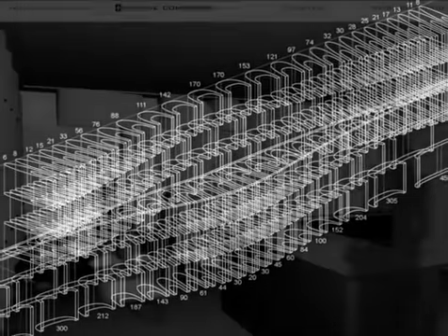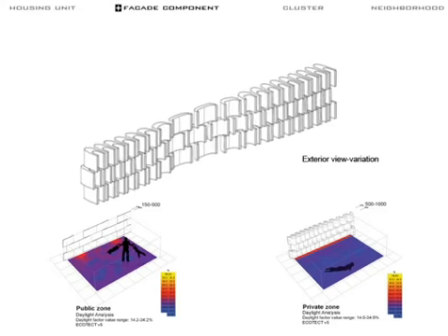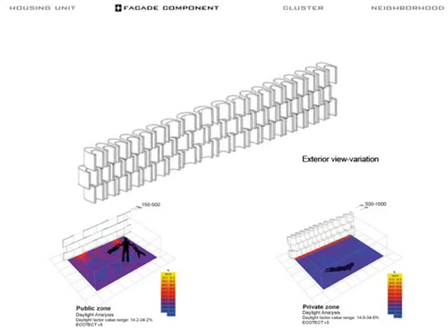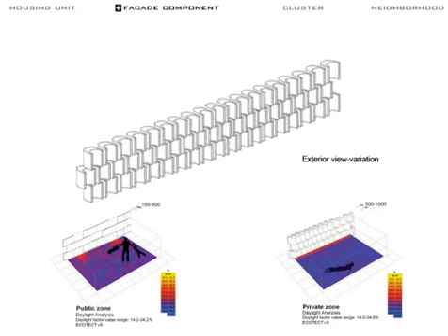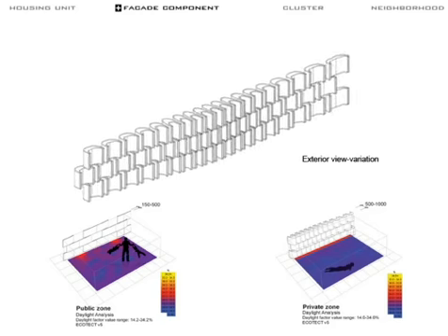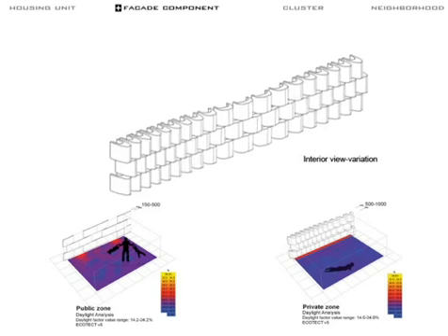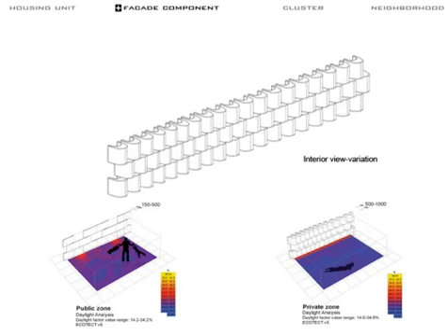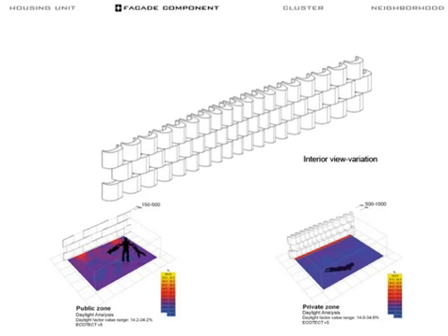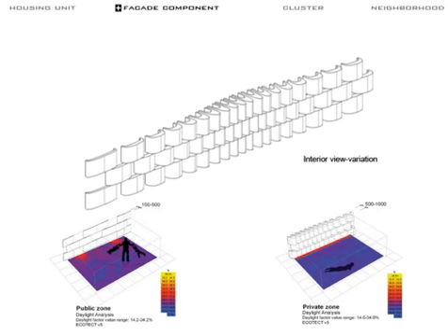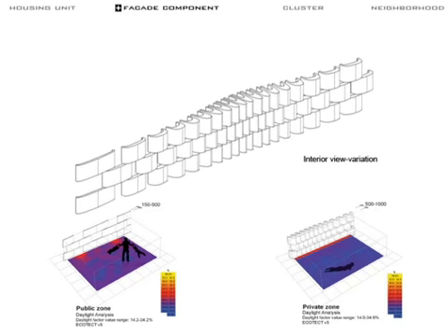When dealing with the level of intimacy as well as thermal comfort, the degree of difference is reflected by its facade element. All components have the same volume. In private zones where intimacy is required, the number of U-shaped components increases. As a result, the components act as vertical shading devices, resulting in deeper recesses which permit less visibility and some penetration to the interior, while their thickness acts as the thermal mass of the house. In communal areas where sunlight entry is preferred, the U-shaped components are wider but thinner, with larger openings for better sun penetration and visibility between inside and outside.